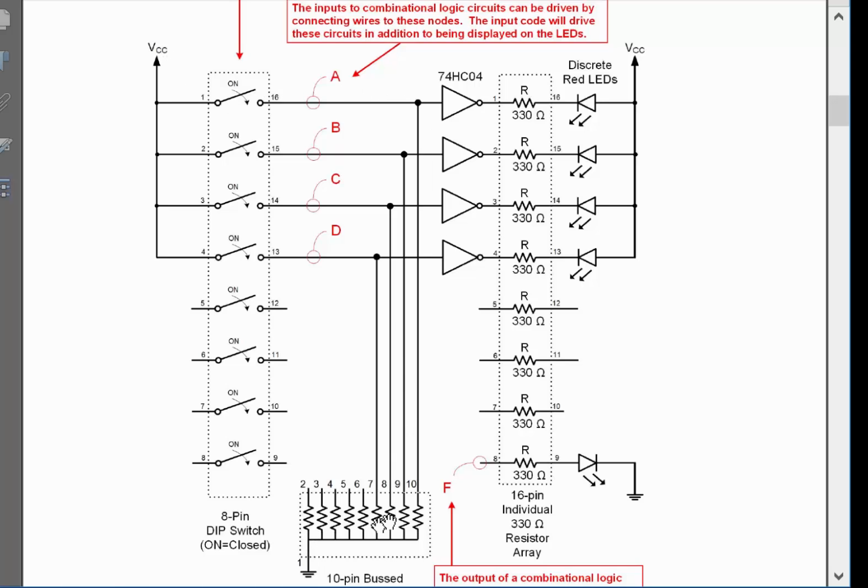When you close the switch, A is pulled up to VCC, and current can flow from VCC through the resistor to ground, and the current will be very small because the resistor is large, due to Ohm's law. The reason that works is that since the resistor is down here, and since we're shorting A directly to VCC, it'll pull A all the way to VCC. When we open the switch, since there's no current flowing, there's no voltage drop across the resistor, so we pull A all the way down to ground. So this is a very common way to handle switches.